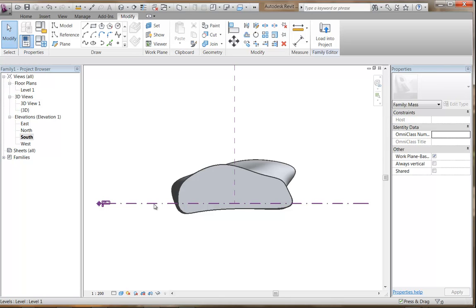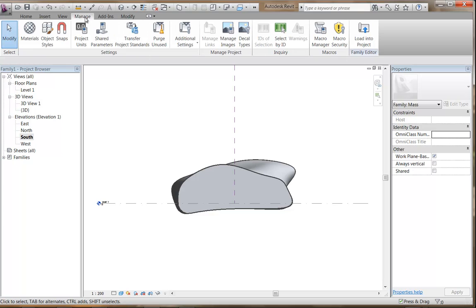If you've got, say, a wall, it's got an object style, and Revit has these things called object styles that basically replace layers. And so automatically, if it's a wall, it belongs to that object type or object style. So this is a mass. This is just an abstract form, and it's actually got its own object style.